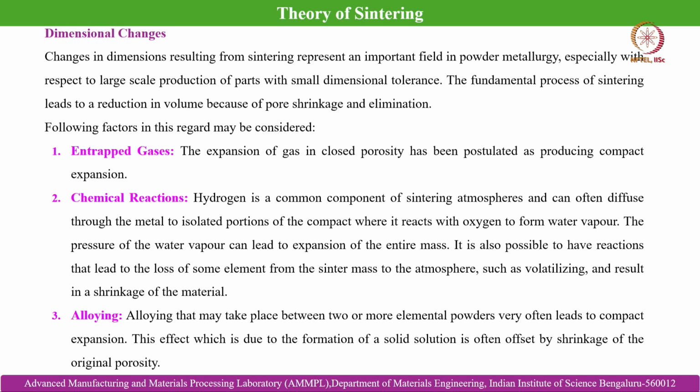It is also possible to have reactions that lead to the loss of some element from the sinter mass to the environment, such as volatilizing, and result in a shrinkage of the material. So this is about the effect of entrapped gases in the closed porosity, and also the effect of chemical reaction, what hydrogen can cause when it reacts with the oxygen and causes water vapor formation. That is another effect that can cause dimensional changes.